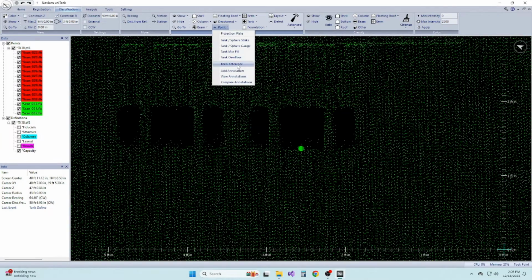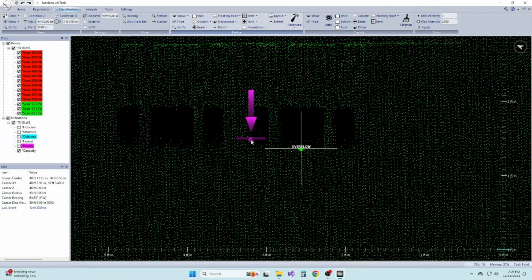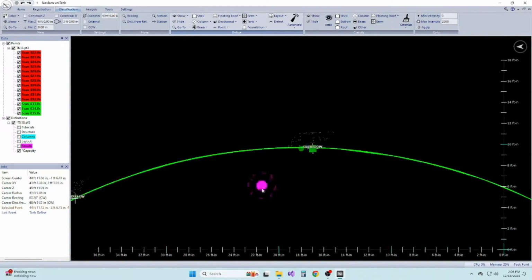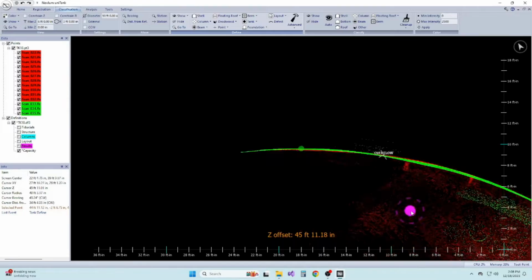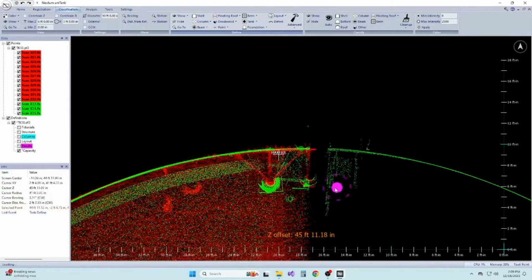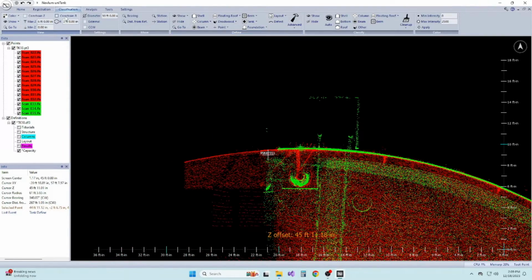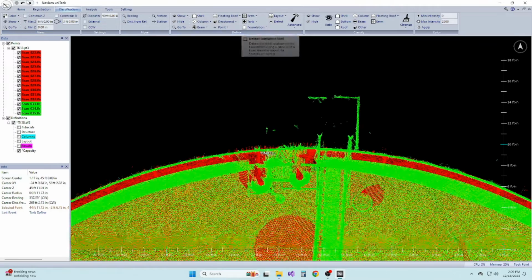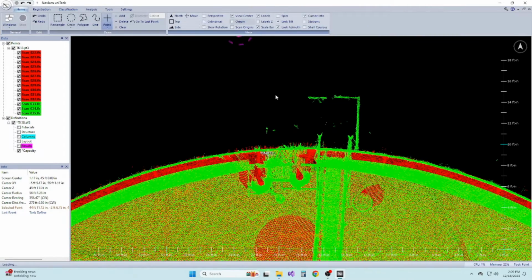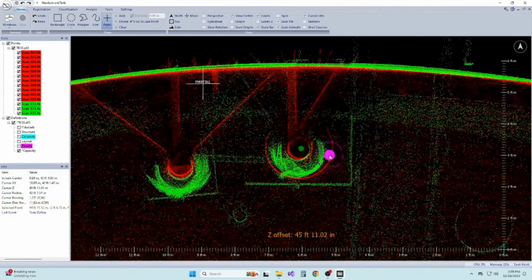Or I can place my view center at the overflow point with no points drawn, and uniTank will automatically use the view center elevation. Overflow points are optional and do not need to be set if you don't have any. You can have multiple overflow points. uniTank will select the lowest overflow point as the controlling height.